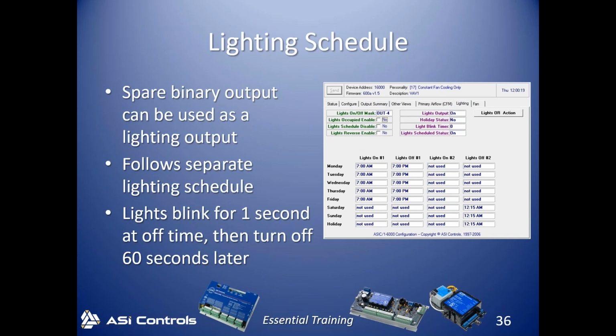And sometimes that's helpful, so that if the controller were ever to fail or power down, the lights go on. So a lot of times you want the lights to fail to the on position. So if there was a problem with the controller and the output turned off, then perhaps you want the lights on. And so let's take a look at that.